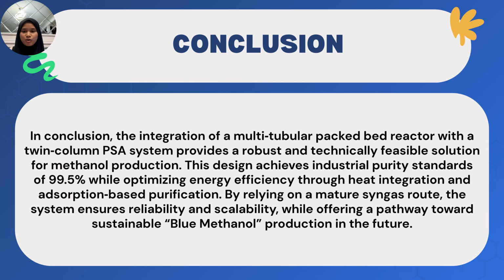So, to conclude, integrating a multi-tubular packed reactor and a twin column PSA system provides a feasible solution for methanol production. This is because it achieves the industrial purity standard of 99.5%, all the while consuming energy efficiently through heat integration and adsorption based purification. This integrated system ensures reliability and scalability by employing the mature syngas route, which offers a pathway toward blue methanol, and it is very beneficial for sustainability in the future.